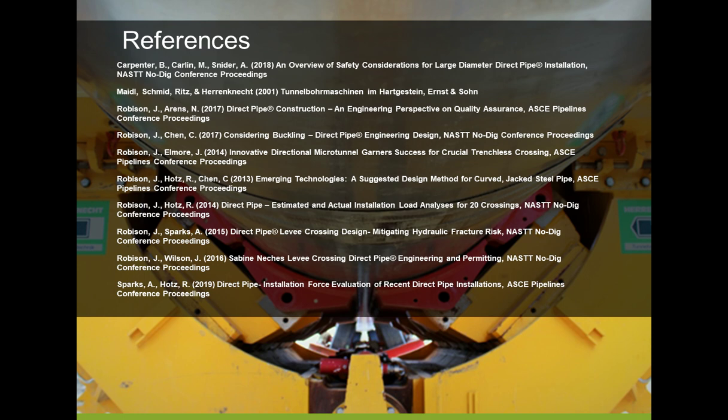How does overcut size on this system compare to a standard microtunnel? What we've seen is overcuts of up to 10 to 12 inches, and we've seen smaller overcuts as well, but for a standard microtunnel, I think you would see overcuts of around an inch or two, much smaller. So the overcuts can run quite a lot larger here, and I think part of that is opening up more hole to push these things around curves is important.